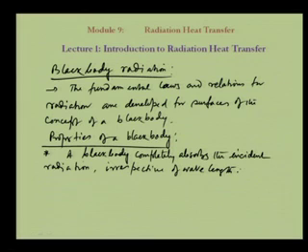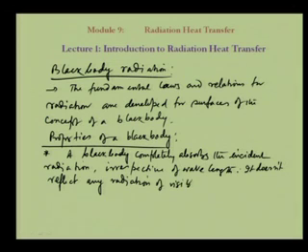And it doesn't reflect any radiation, of visible range, because we can say only of visible range. That means what? We have told already that absorptivity alpha is equal to 1, but it does not go for any kind of reflection. So, rho is equal to 0, and it does not go for any kind of transmittance. So, tau will also be equal to 0, that is what we have seen.